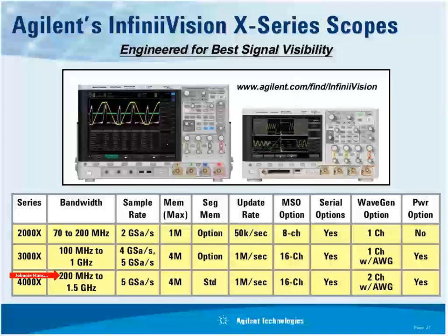All the measurements I showed today, except for one, can be performed with a 2-channel scope. The only measurement that requires a 4-channel scope is the efficiency measurement, which, as I mentioned when I was going over that, you can actually do in a two-step process. So you don't need a high-performance scope. You can get away with 100 to 200 megahertz.